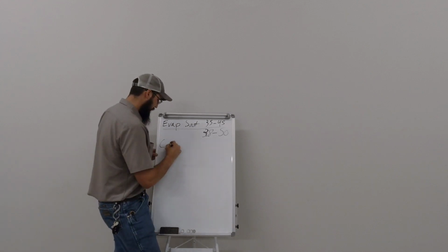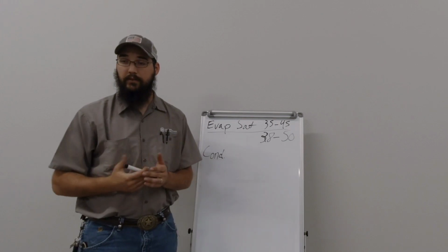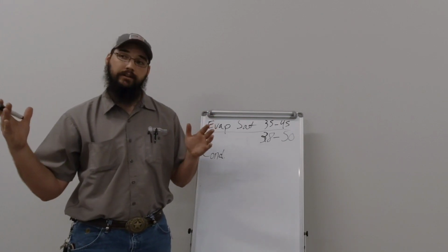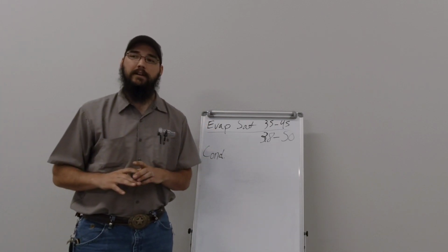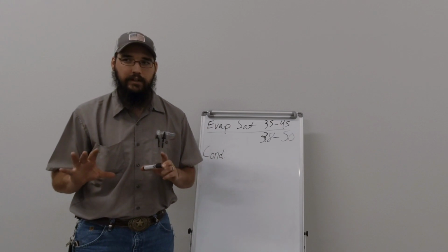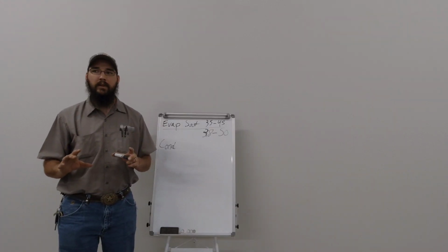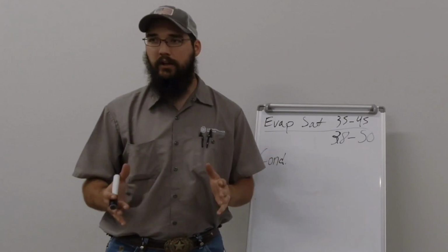Condenser, what are we looking for? Don't let it go below 90. Well, I mean, it rains, but. Depending on the system, yes, 15 to actually about 30. 30 to, depending on how old and decrepit it is, 35. But it's usually because there is actually something going on there. 15 to 30 is the set standard range.